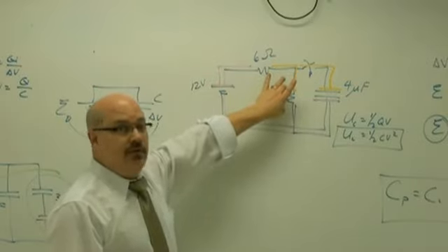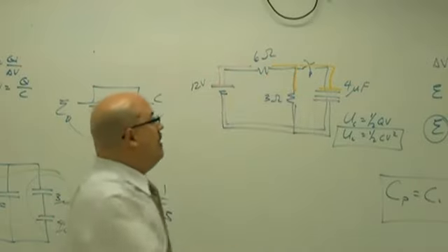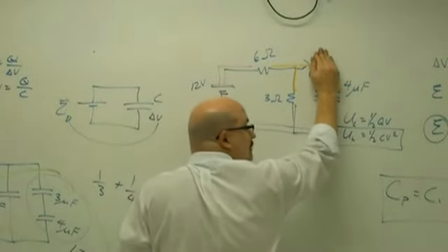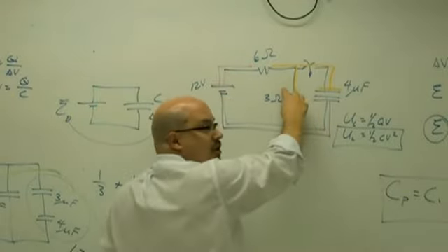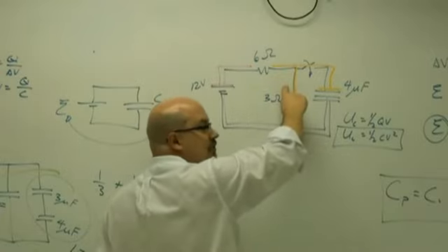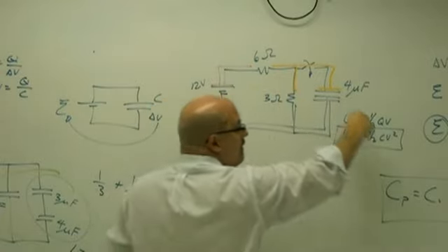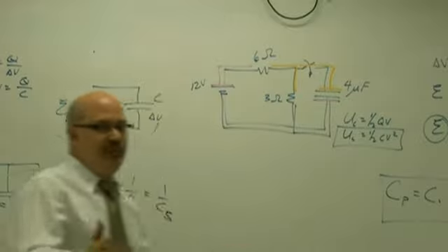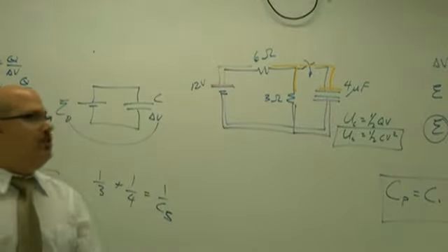That's important. So what you'll do is you'll just forget about this for a second, figure out the current through here, and figure out the potential difference here, and then whatever you get here, that's the voltage you put in there. Not that bad, you just got to know that that's what you do.